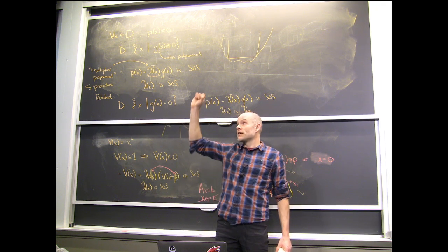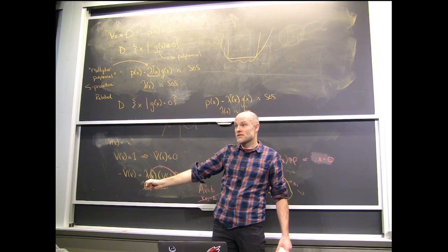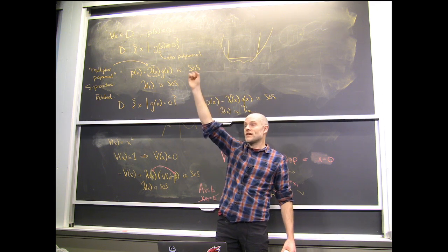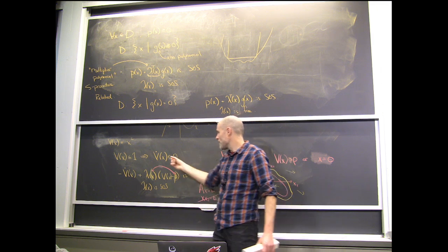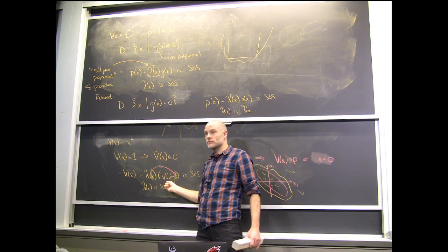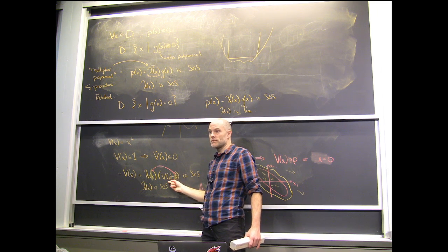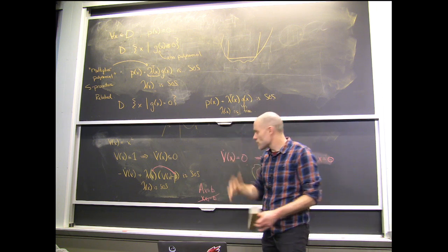V dot is going to be increasing in some places. I want to say that at least in some invariant sublevel set, V dot is going downhill. That would give me a region of attraction. So that's why you have to do this multiplier trick. Say V dot only must be less than 0 inside this region. Good? Okay, so let's just imagine what you can do about it.